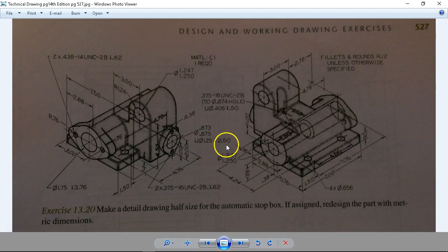Spot face of, or counterbore of 1.25, 2.5 deep. So I don't see that hole coming all the way through or to the intersection. So unless the call out is for the 0.25, but that's open to too much interpretation. So I wouldn't expect to see that on our CSWA exam. There would either be a side view or detail view that would call that out. So I have a knack for finding the ones with weird errors.